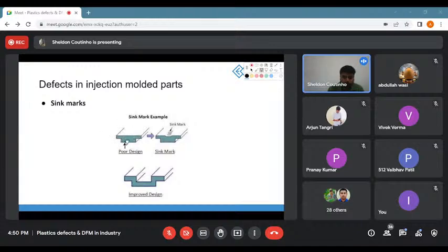Now, if we consider this lower surface to be the aesthetic surface, this is the shape that we want on the outside. So rather than having a proper solid plastic component like this, where this entire thing is going to be full of plastic, what we can do is take this part and instead of having a straight wall below, since the upper part is the aesthetic component, we can go like this and like this. So I did that a little wrong. Just imagine this part and this part has the same thickness. Okay, so we can ensure that there is uniform wall thickness.